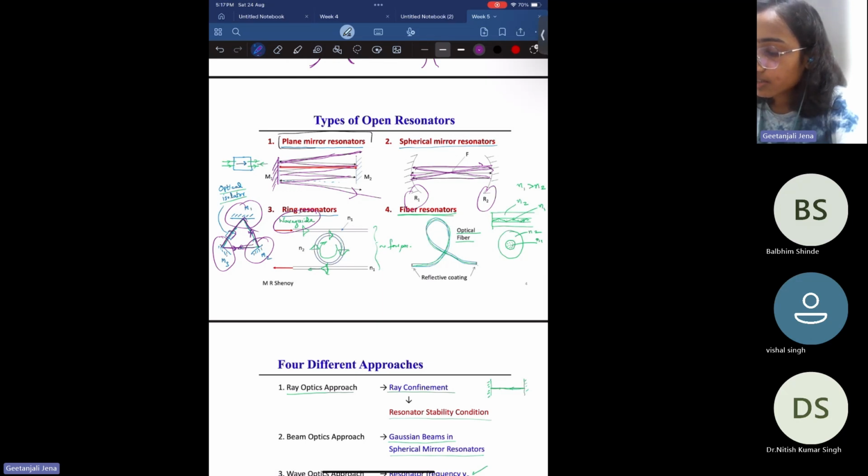So if you see this third figure, it is one waveguide, which has refractive index N1, and one ring resonator and another waveguide here. When light is incident through this waveguide, what will happen? At this point where the ring resonator is closer to the waveguide, the light will get coupled to this ring resonator and it will oscillate inside it, either clockwise or anti-clockwise.